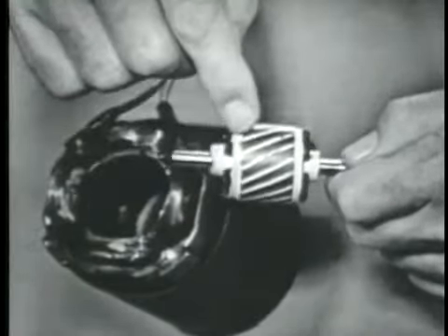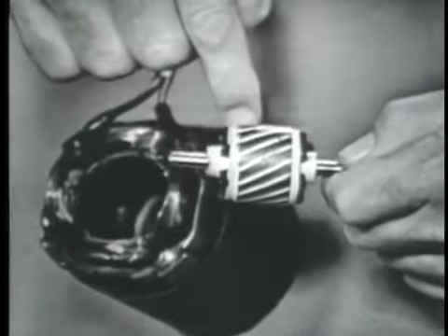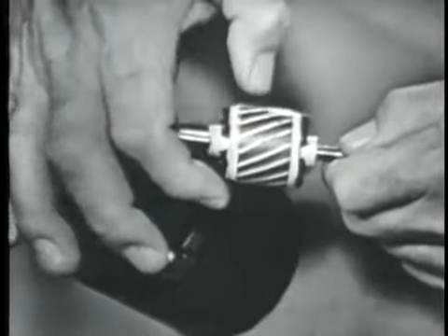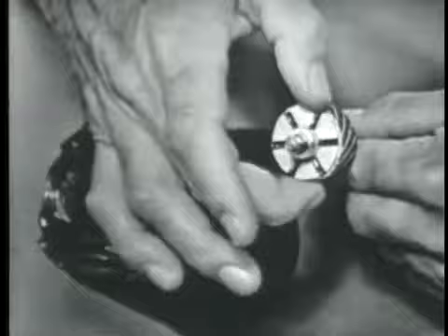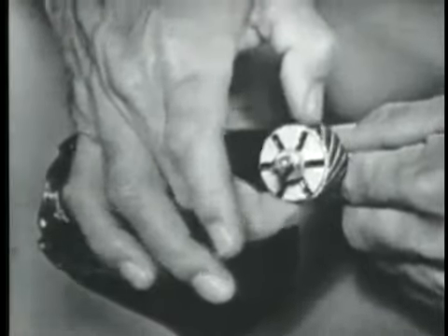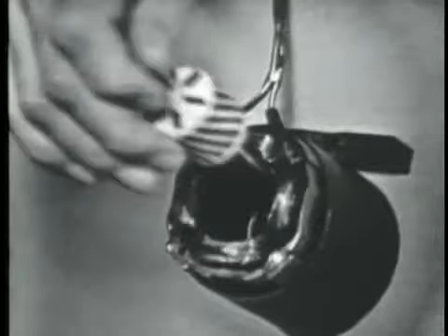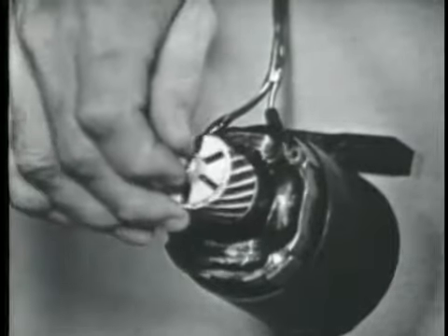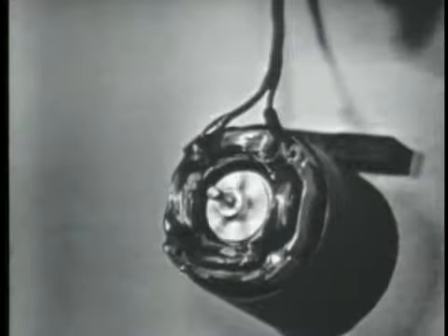Now, as the rotating field goes around this rotor, current is caused to flow in the rotor, which sets up a magnetic field, and the rotor develops a north and a south pole. Once we magnetize the rotor, it has got to follow the rotating magnetic field, as you've already seen, just like that. The rotor follows the rotating magnetic field as soon as it becomes an electromagnet.